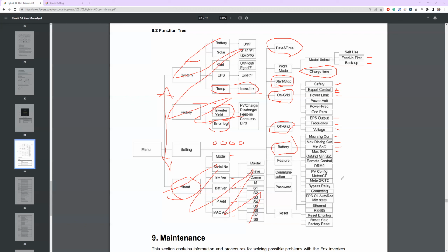And even with this maximum state of charge set, solar still charges the battery. So during the day, the solar can still charge that battery, but I'm not using the grid to fill the batteries up. Another way around just leaving this at 100% is reducing the time window that you're force charging. So if you know it's going to be okay weather, but you want a little bit of force charge, just force charge for half an hour or an hour instead of the full 4 hours if you're on an Octopus Go tariff. So they're really settings that you can manipulate to affect the longevity of the battery.